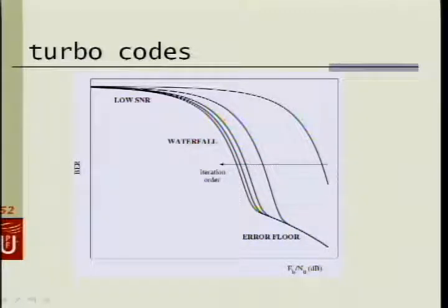So turbo codes work well if the error probability falls in the waterfall area. They don't work well if we need a large value of Eb/N0, or a very low value of error probability. There is always a value of error probability that yields this change of slope, in which case it's better to use a code that has a larger minimum distance.